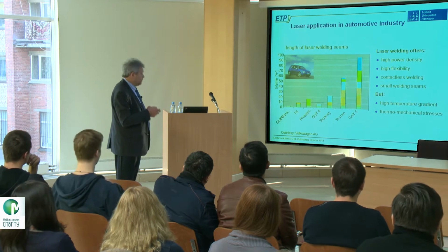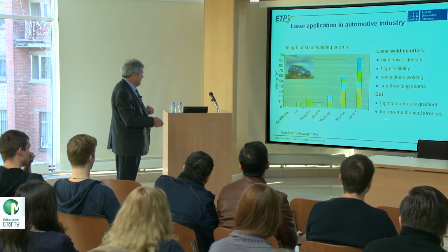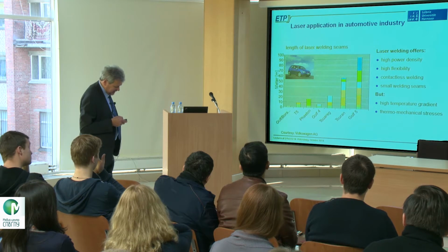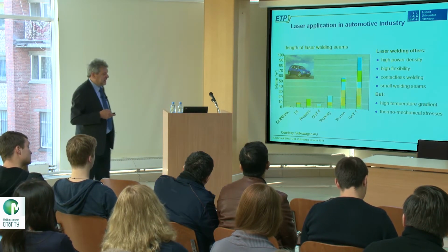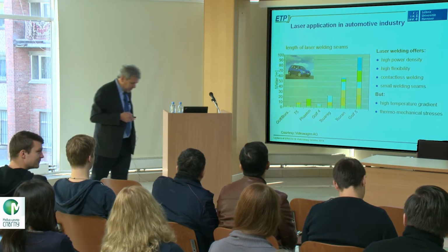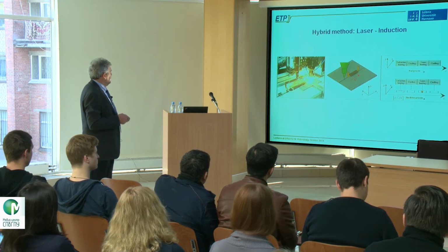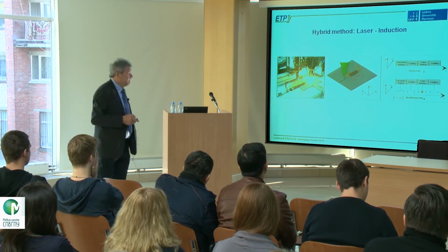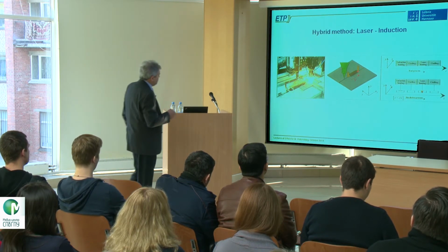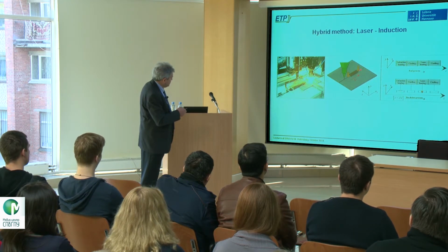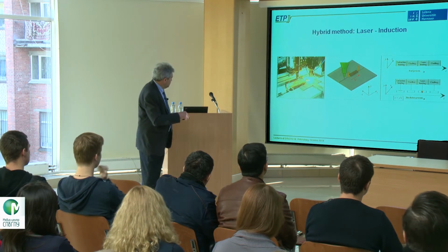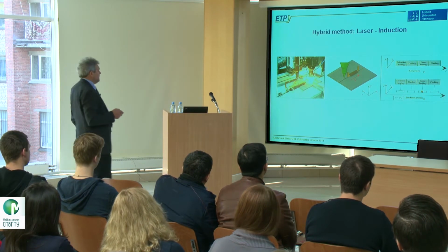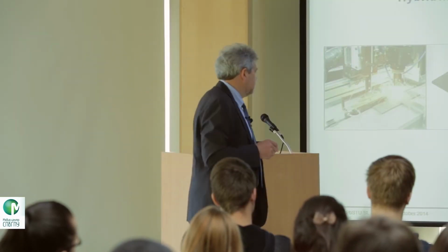But as I told you, we have then these high temperature gradients, high thermal stresses, and therefore we have carried out a lot of research projects in the last 8 to 10 years, together with laser experts, with our Laser Institute in Hanover, to investigate this and to realize this combination. And therefore we developed a new simulation tool to combine laser and induction, also sometimes arc welding for thicker strips. We call it hybrid method. Here we have a typical line inductor, which of course heats the seam, and this is the laser. In reality you see here again the inductor, and this is the laser. You can use the heating before the laser welding or after the laser welding. Both are possible. We have investigated both.